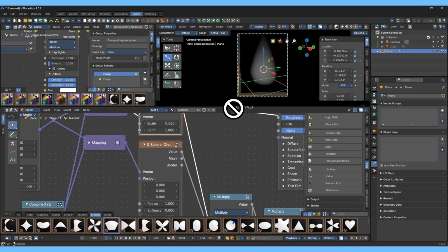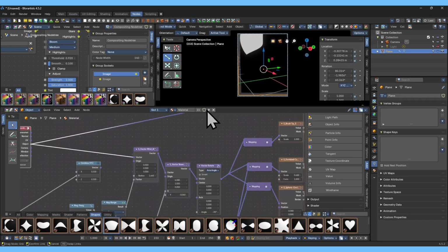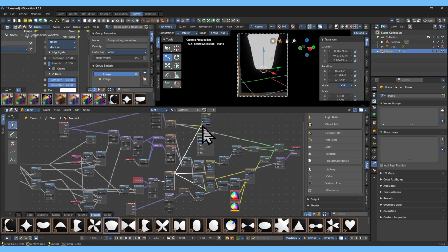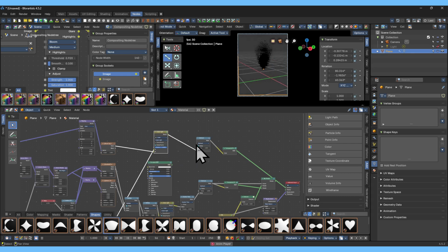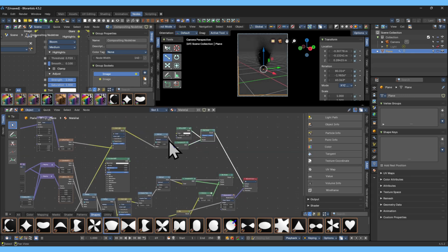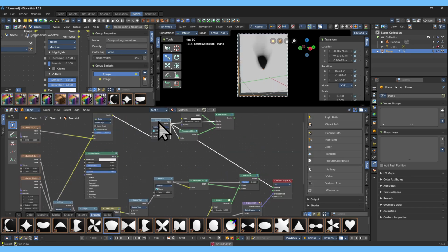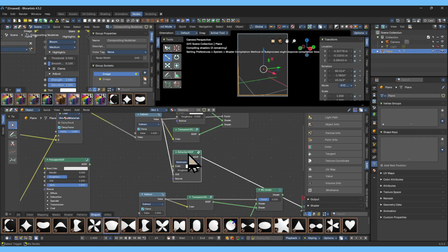So let's add in a bit more touch and create a new shape. Align it to the top using the brush tip shape from the Bforartists assets. Then I use the same noise deformation and linear light that back in and create a smoke shader or mask, and invert it and then composite back in.